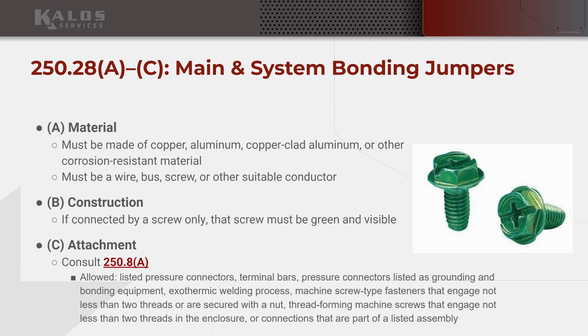I've been in this situation before myself where I've got to ground this box and I don't have any 10-32 screws. I've got these tech screws, so I take one out of my bag and I screw the box. Honestly, I'm not saying to do this, but if the alternative is I'm not going to ground this box, then use a tech screw. But the right way to do this is with 10-32 screws. And if you're going to make heavy use of self-tapping screws, then get ground-rated self-tapping screws.